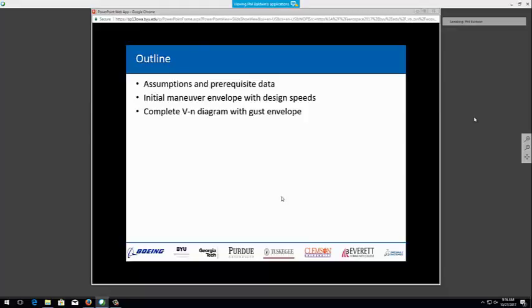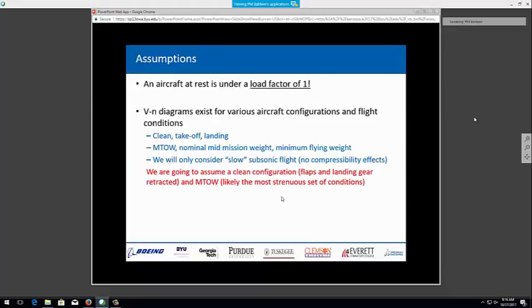So coming down, you'll flutter and break the wing. So we need to take a look at that. But typically, you want to design for about 40% above your cruise speed. The VNE, velocity never exceed, is what they call placard speed. So every aircraft has a placard on the control area that says this is the maximum speed you can fly.